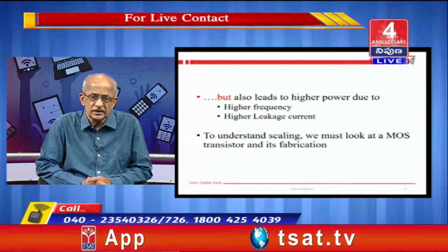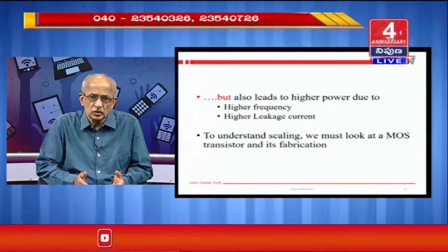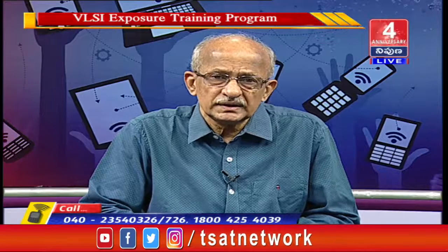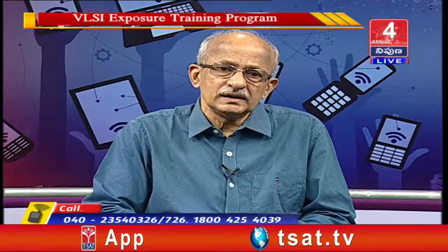Low power VLSI designs are gaining momentum, and many of the chips have got low power features incorporated into the design. One of the simplest low power features to be incorporated in any VLSI design is clock gating. You switch off the clock to some portion of the circuitry which is not being used, and therefore reduce the power in that particular area of the circuitry, because every time you switch a particular node, power gets consumed. Why does power get consumed when you switch a node? We will see that through diagrams a little later in the day today.